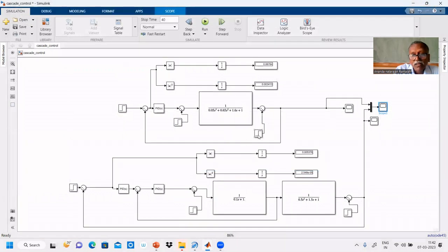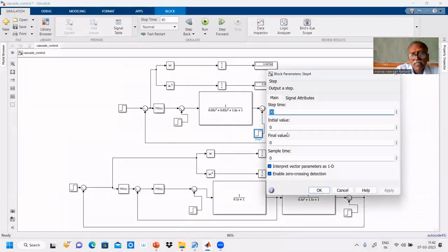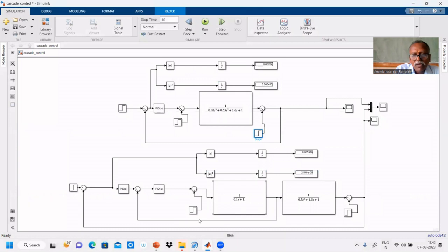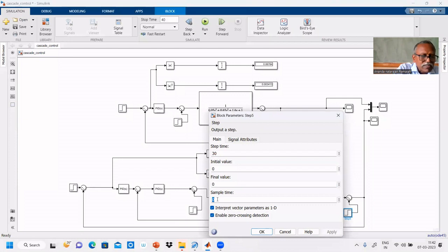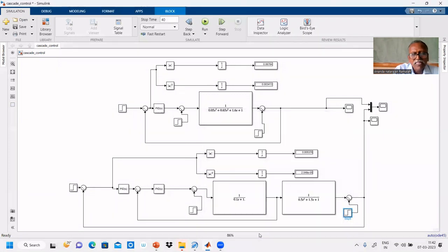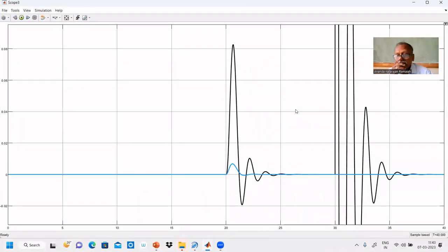Let us check for change in TI, that is inlet temperature of feed. That has immediate effect on the output. That's why we are giving it outside that process. It has immediate effect on the T. That's why it is given here. If you see, for that also, it gives better dynamics. You see here 0.7.